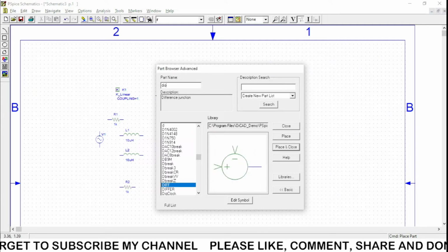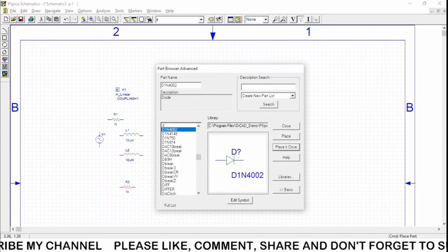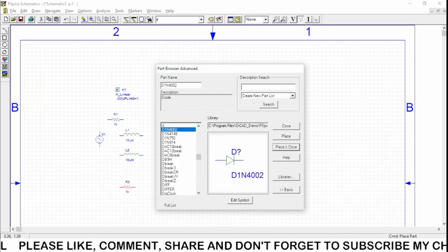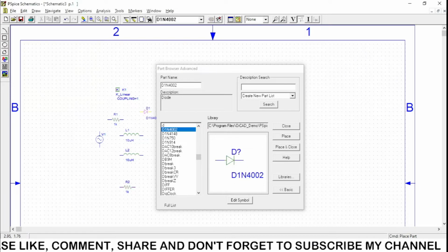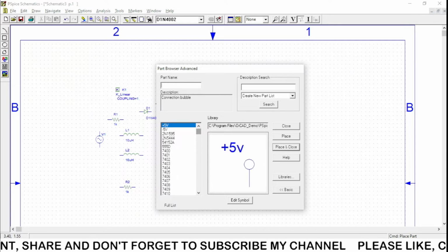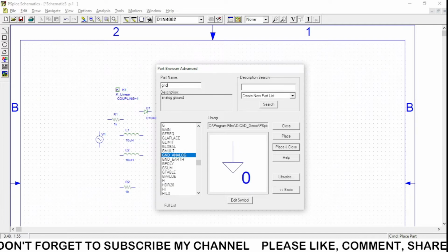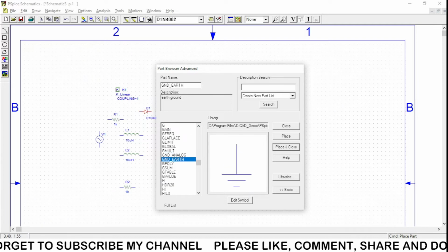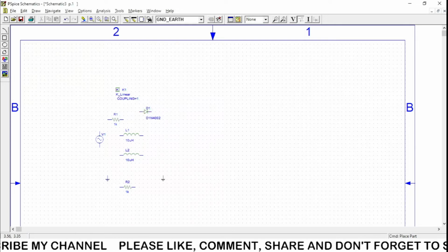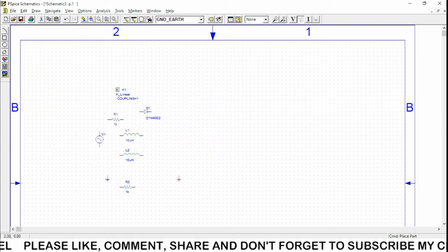Then we need a diode. We can take a diode which has a model name. We cannot take just the D, as it does not have a model, so it will show some error. I'm going to place it over here, and then we need ground. In a practical circuit we have AC ground, but in this circuit we need the ground earth concept. So we require two grounds actually, so I'm putting two grounds here, one for the input side and one for the output side.